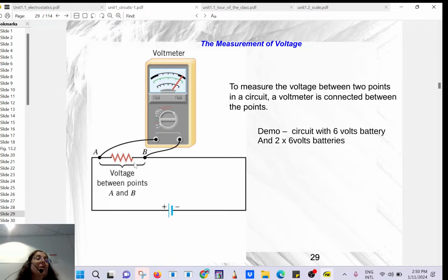Even though the voltage was 120 volts AC, which is quite dangerous, the current didn't flow through it because the resistance is very large. But if instead you put it in amps, that would be very bad, because then there is no resistance, the current flows through it, and I would be electrocuted. So make sure the knob is in voltage.